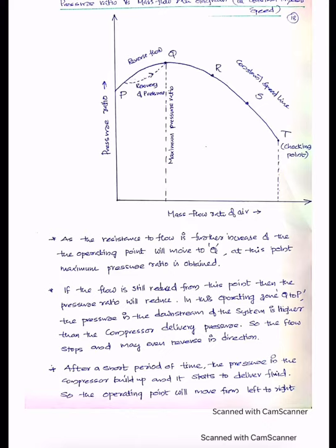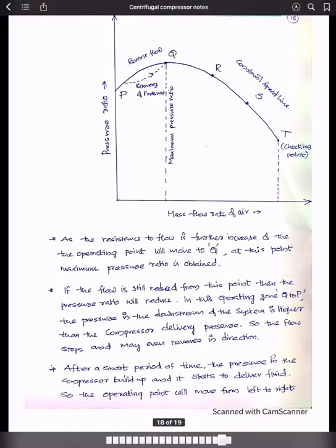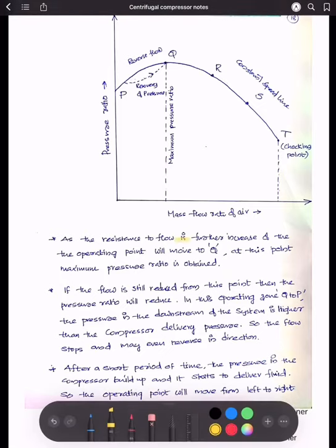Clear? Now, every compressor has an optimum working condition. By looking at the specification of the compressors, we'll decide an impeller speed and a pressure ratio. Let's just say S is the design point. It is the optimum working condition. Now I'll mark where S is. Now S is the optimum working condition. It is called a design point. Now what happens when we decrease the mass flow rate?